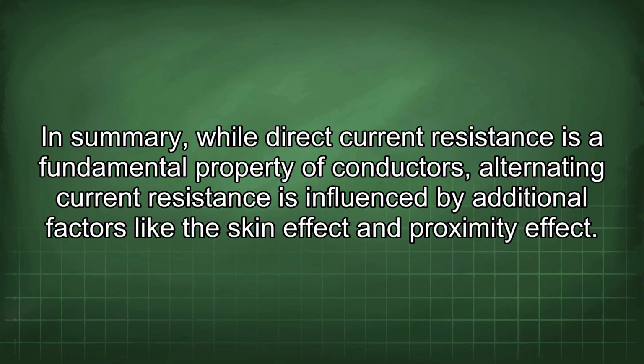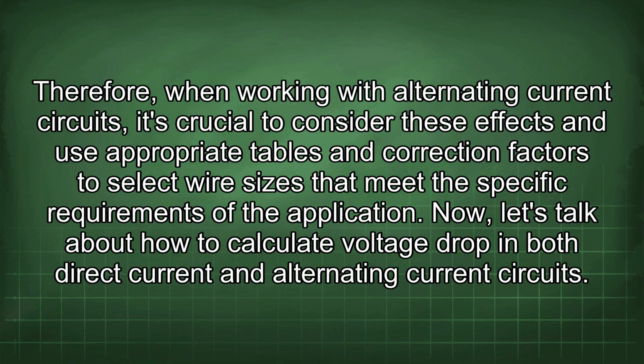influenced by additional factors like the skin effect and proximity effect. Therefore, when working with alternating current circuits, it's crucial to consider these effects and use appropriate tables and correction factors to select wire sizes that meet the specific requirements of the application.